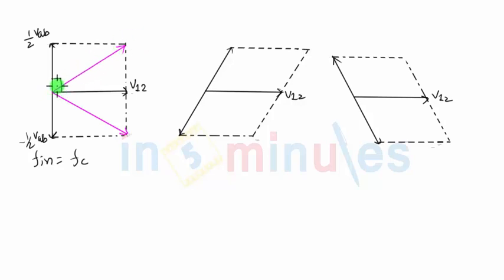The vector which I have drawn in pink color becomes the resultant vector, and as of now I'm going to give it the name VAO. We will see where VAO is in my circuit diagram. And when I add the primary voltage with the voltage in the second half or the lower half of the secondary, I will get another resultant phasor, and I'm going to call this VBO.